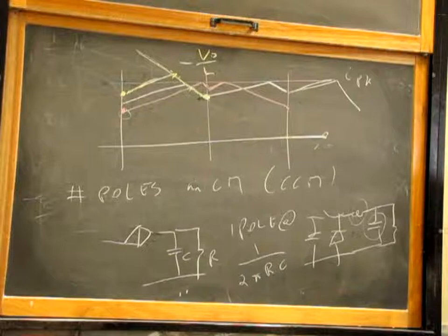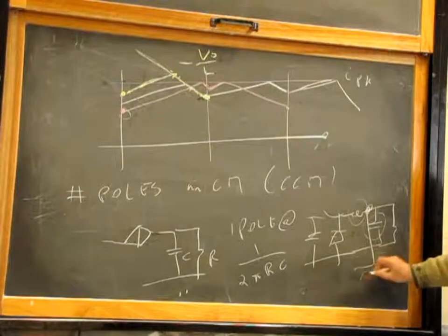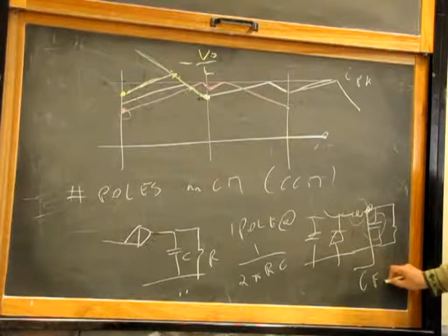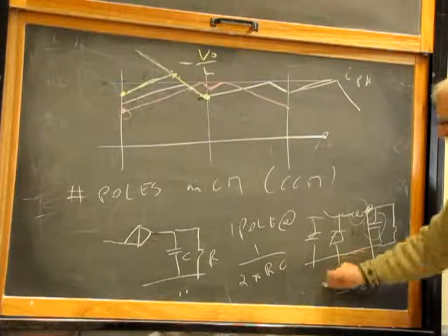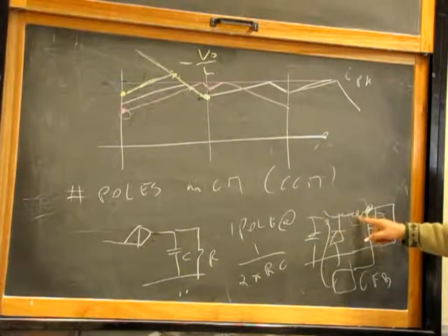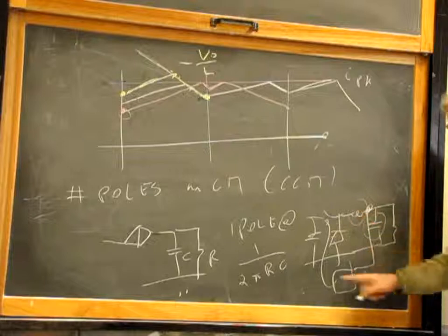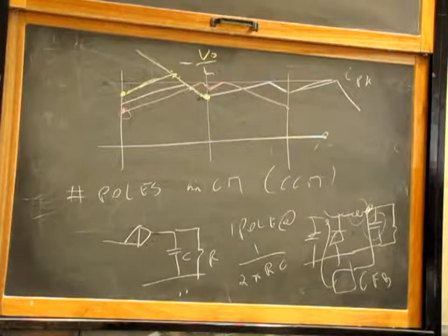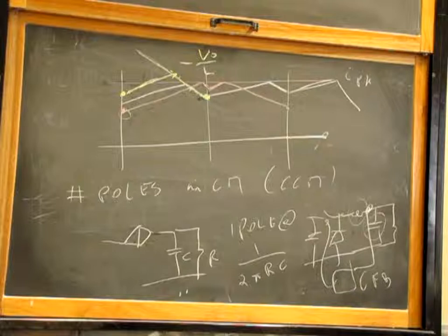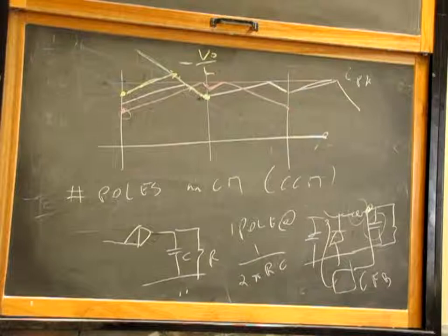And if you consider that you have a feedback over here, current feedback, and you go to a controller and you go to control the switch to keep the inductor current constant, that is just a feedback. Feedback cannot cancel, cannot destroy, cannot manipulate a pole. Feedback, give me the magic word, moves poles, scatters them around, but does not cancel them, does not remove them. They are still there. They are just moved away.